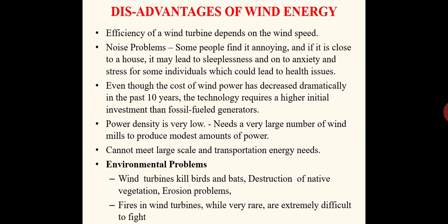Now coming to the next disadvantage: power density is very low. It needs a very large number of windmills to produce a modest amount of power. If you want to produce power in a large amount, then we have to install very many large windmills, which is very costly. With this power production, we cannot meet large-scale and transportation energy needs. That is another disadvantage as far as wind energy is concerned.